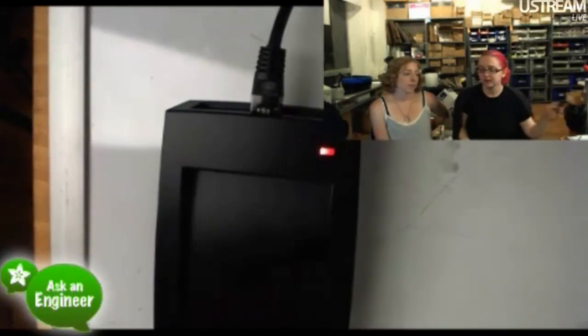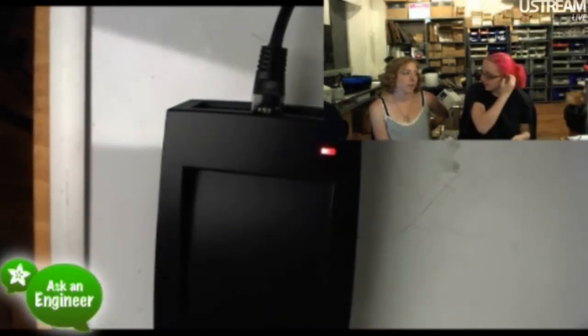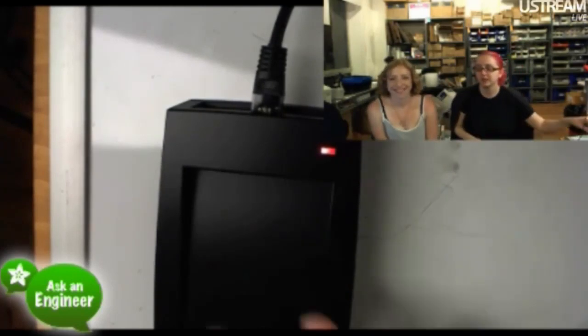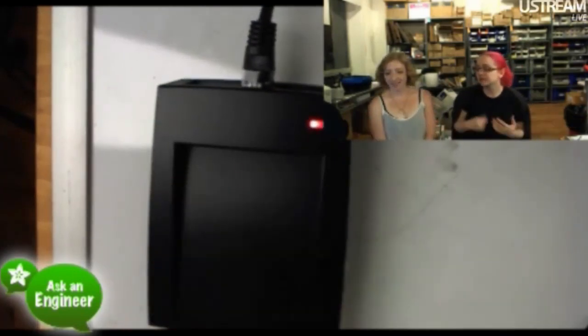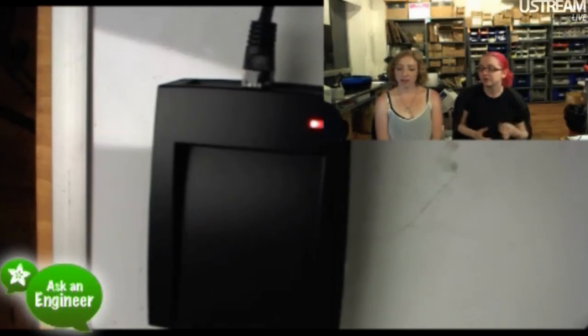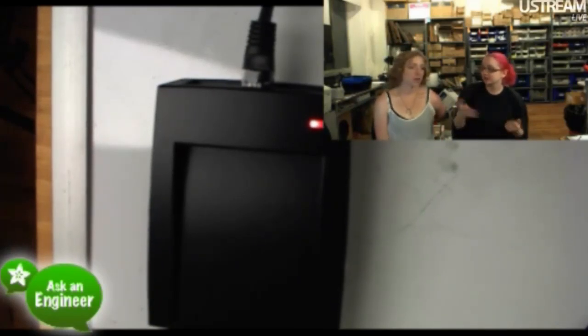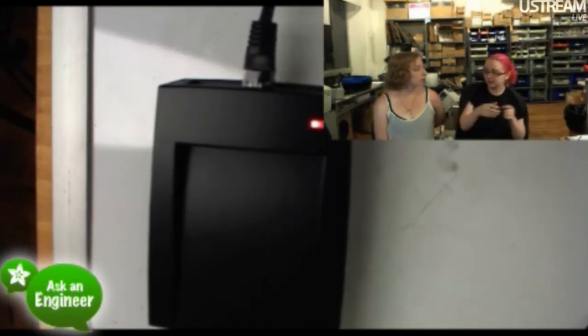It has a little blinky light. You can open it up and remove the beeper. It's literally just 2 wires. You just cut them and it'll stop beeping, and you can remove the LED too. So it's basically just a nicer version of the RFID reader, but it doesn't do any kind of NFC stuff. It doesn't read or write the tag contents. It's only for reading the MIFARE tag IDs. So it's not for high security stuff. It's just for when I want to give out a bunch of tags, and each tag has a permanent ID, and they can read them.